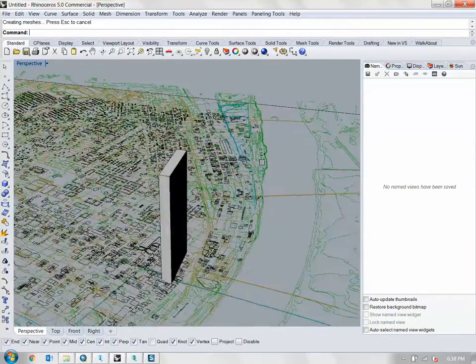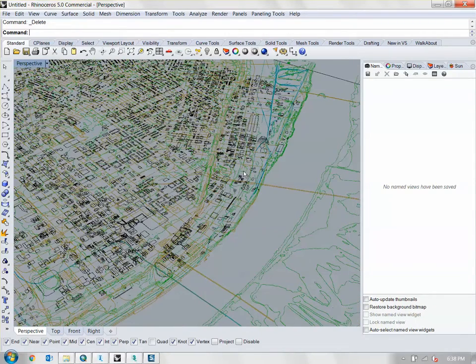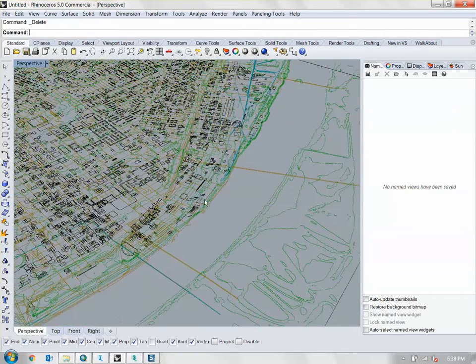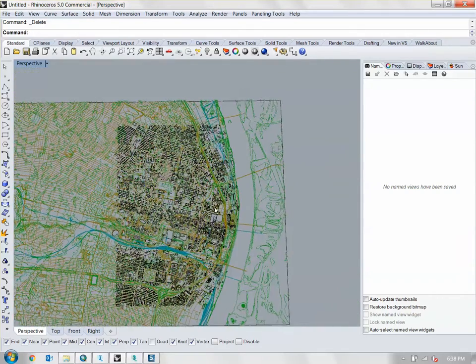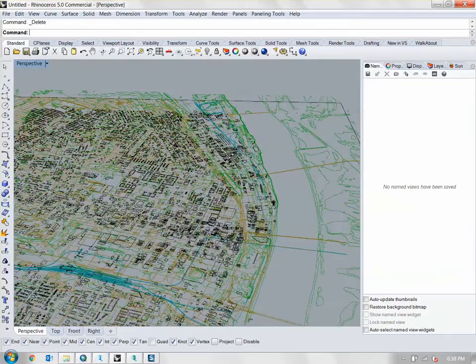It's okay with rectangular geometry, but for more complex geometry, what happens is that it sometimes begins to have a flickering look. It looks like the geometry is broken, and that's simply because the units of the coordinates of all the geometry features are just way too big.